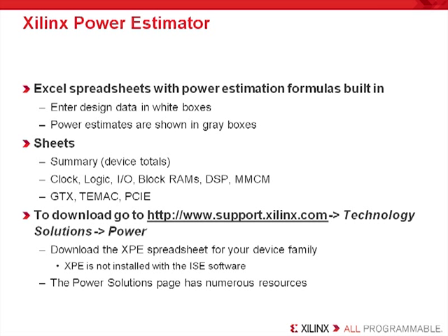Unlike data paths that are mapped to LUTs and registers, these dedicated paths that include the dedicated resources effectively only have a programmable routing to the resources. The actual logic resources, again, are fixed in the silicon. Another reason to use the dedicated resources is that compared to soft implementation, that is one that is synthesized for LUTs and registers, the speed by using the dedicated resources is significantly higher.